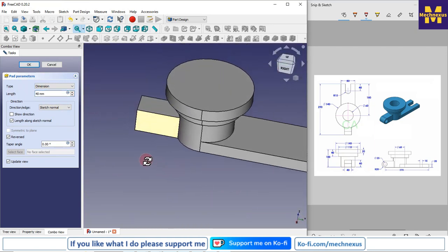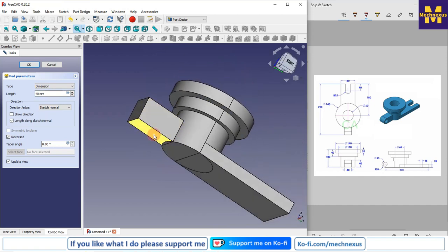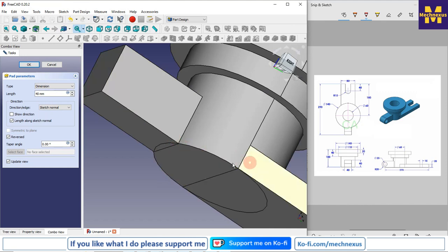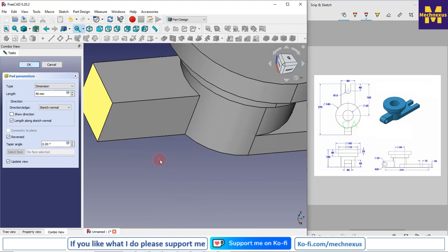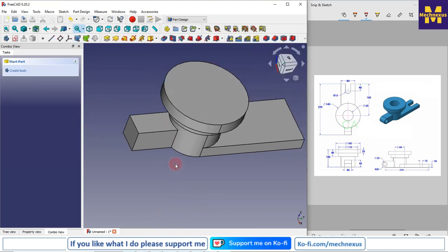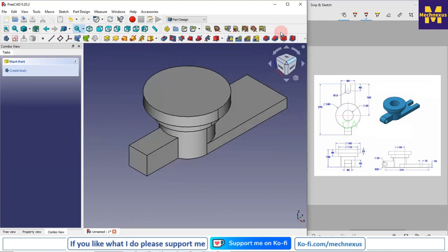The problem we were facing was that the bodies should depend upon each other. In the last sketch, we projected this arc, so it was not intersecting with our main body. That's why we were facing the problem. Now say OK, and now we will make the slot here.